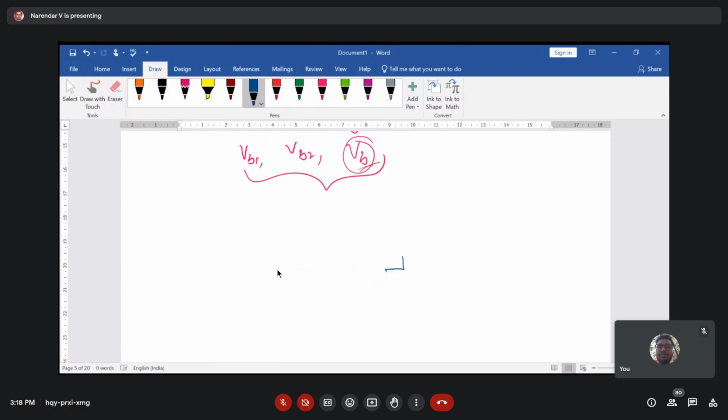Let's use a MOS transistor as a current source, obviously, and this is our NMOS transistor connected to ground. Here we are expecting that the current ID should be constant, and we require the voltage VGS, or the VB voltage that you are talking about. And how do you apply this VB voltage? We are taking a battery here, called VDD, and we apply a potential divider circuitry here.